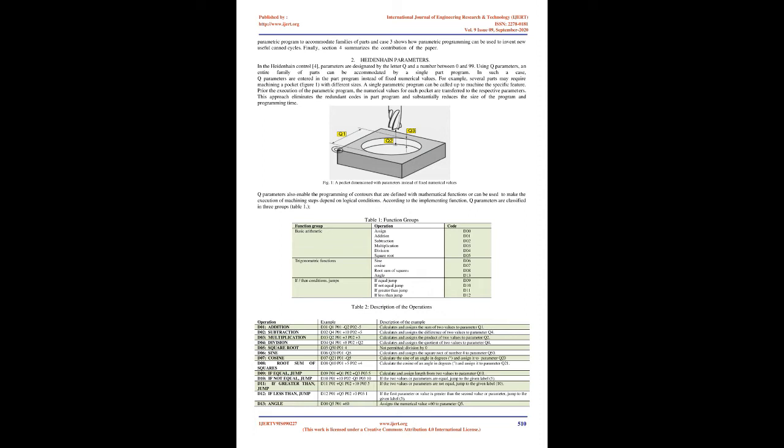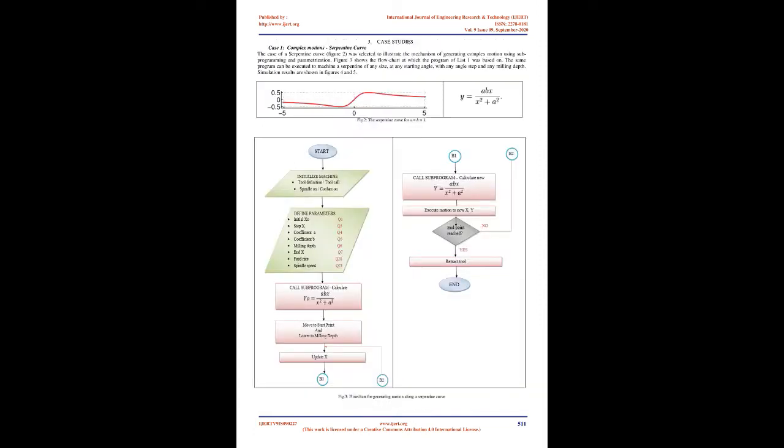For example, the statement. Each of the codes other than G and M has a unique function. The G and M have many functions depending on the following 2-digit number. These functions have been standardized and are commonly known as G and M codes. Generally, a G code, named preparatory function code, defines one type of motion or one mode of operation, while an M code, named miscellaneous function code, turns various operations on/off, e.g., coolant flow, spindle, etc. It must be noted that not all the possible code numbers are allocated, which means that control systems manufacturers can use those remaining for whatever purpose they wish.